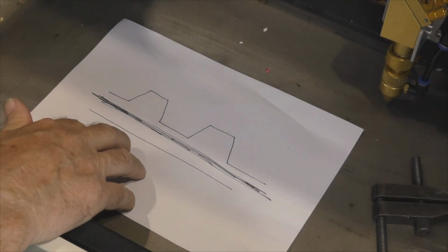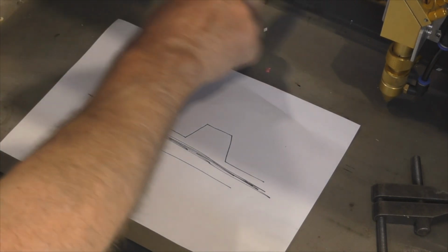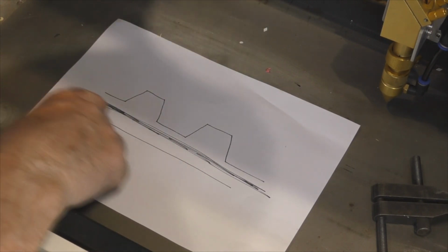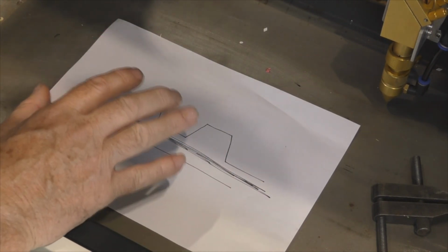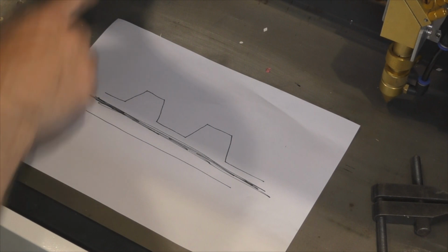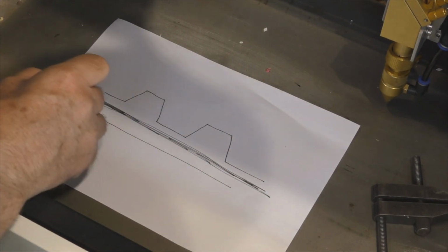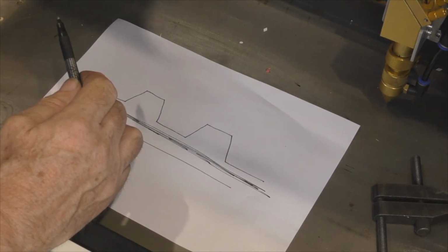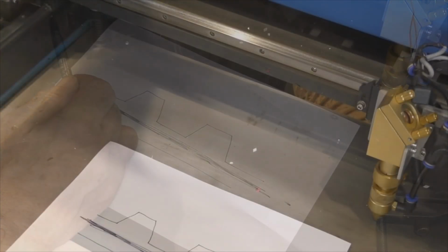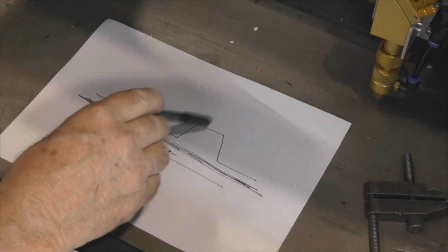Now, here we've got a very crude diagram of this timing belt. Along the back of this belt, buried in here, we've got a load of strings. Those strings could be made of all sorts of materials, but when I burnt the belt on here with my Chinese pizza oven, I discovered this. There were glass strands in the belt. Yes, these glass strands are getting closer to my rod of steel in the servo system model. So we might not have too much stretch in there. It looks like a fairly stiff system that's been designed here, with one weakness, and that is these teeth.